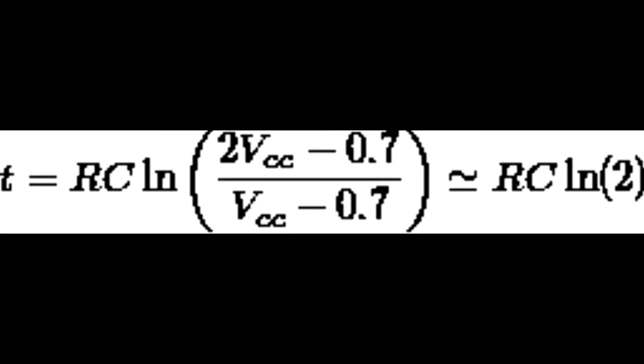For the design of the circuit, it is known that the capacitors are charged by R1 and R4 faster than they are discharged by R2 or R3, because when charging from state 1 to 2, we want the other capacitor already charged, so R1 is less than R2.